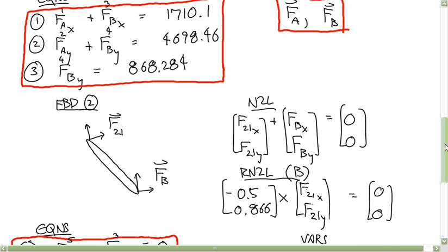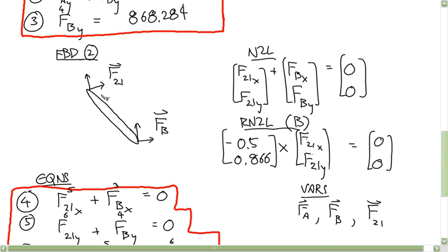And then I isolated member two. I called this member two and isolated that just so I could keep consistent with my convention of where the force is applied and I wouldn't have to deal with that external load. So I took the second member. The only forces are these. By the way, if you want to find shortcuts, this is a two-force member. You could treat this as just a scalar force going that direction and an equal and opposite force over here. Cuts down the number of variables.